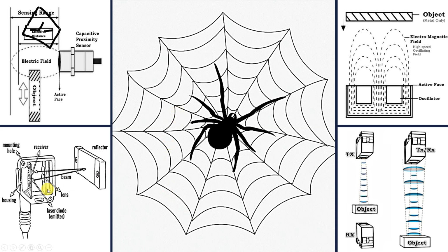The most obvious is going to be a laser light, or in the case of the photoelectric sensor, they generate a beam of light, and if any object touches this beam, it is going to generate a signal. The less obvious technologies are the electrostatic field used by the capacitive proximity sensor. It uses parallel plate capacitance, which generates an electric field. If the object enters this field, this is detected as a change and the capacitive sensor gives the signal.